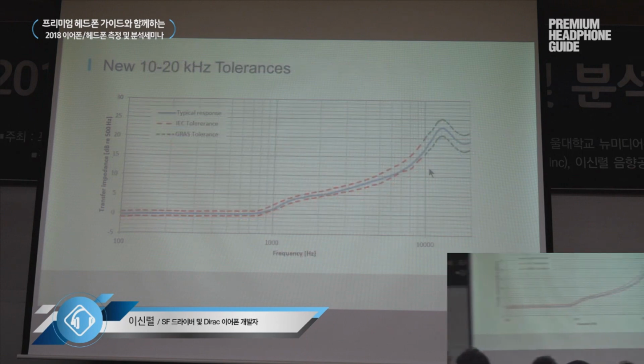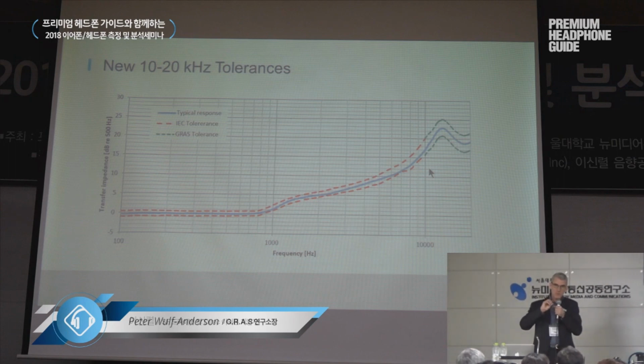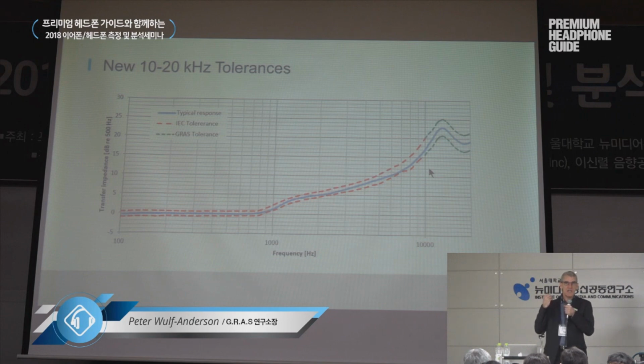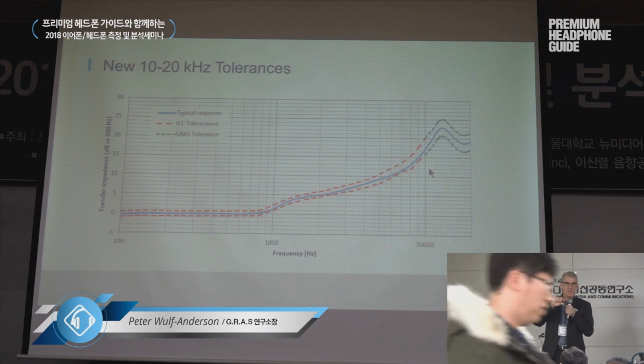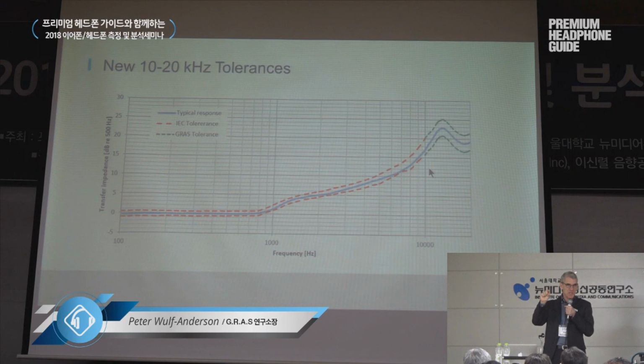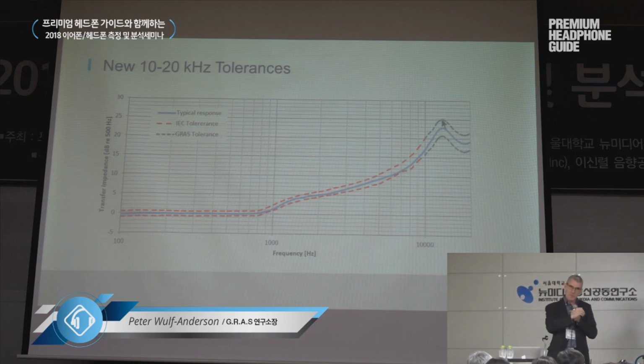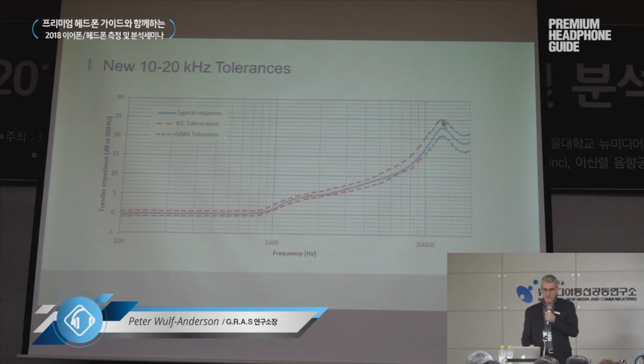So as mentioned, we managed to extend the tolerances, which means that now your measurements are much more repeatable because the sharp resonance is not there anymore, and also the tolerances are now extended. So you can do from coupler to coupler, and in the same measurement, you can rely on a much higher repeatability of your measurement.